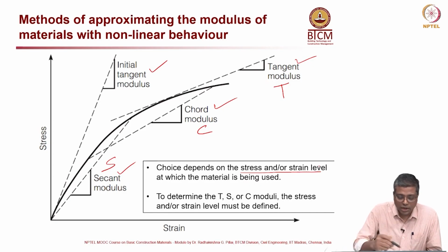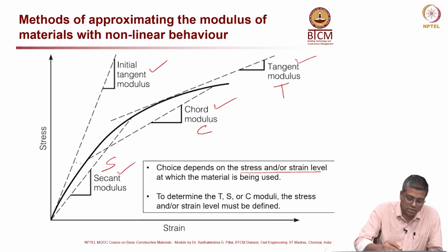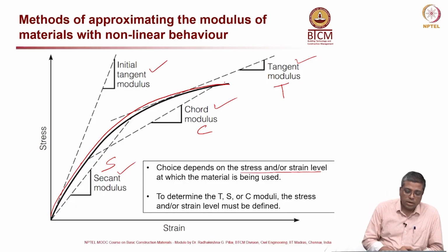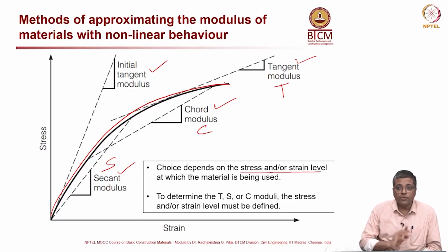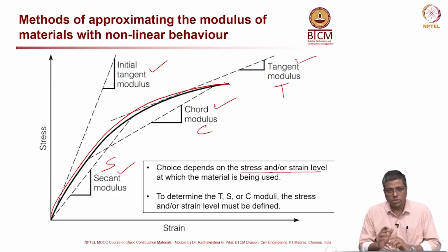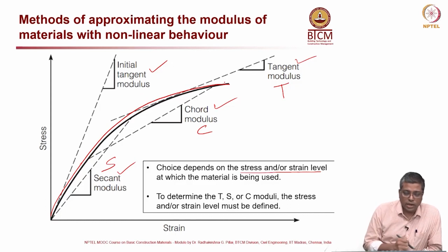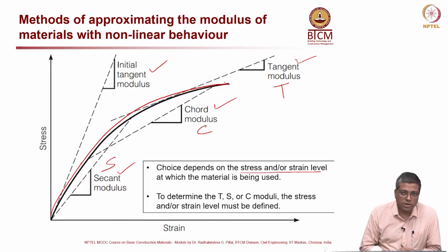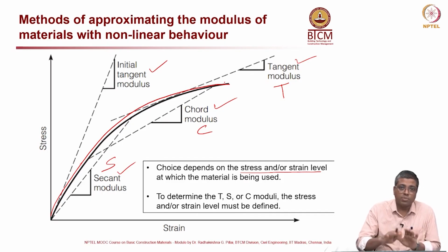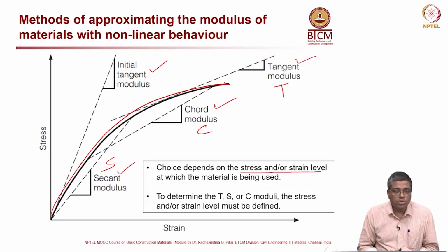So, when we get this stress strain graph, you can see it here, this thick black line. Okay. When you have a stress strain graph of a material, and if you know the typical stress level the material will go through in service, based on the applied loads, I can calculate that in-service stress level, and then use that value and these types of curves from different materials to compare.